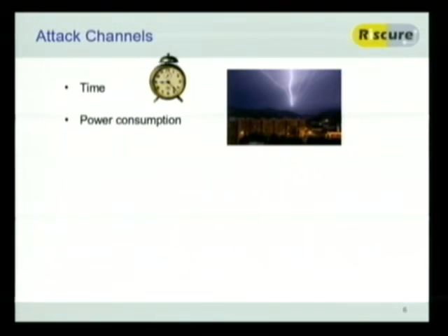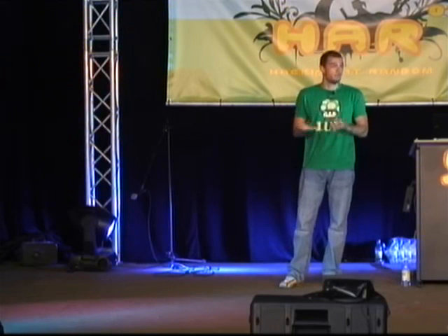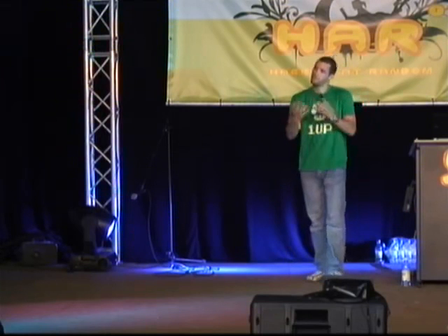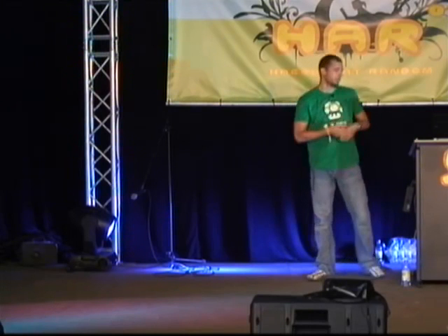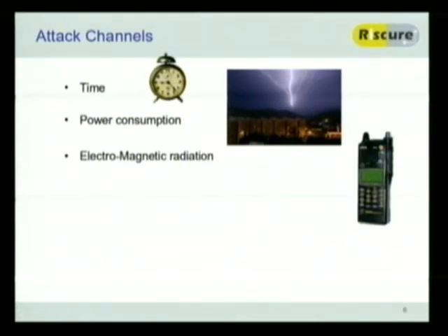Power consumption is one of the major side channels that we're going to be looking at. You can imagine that each device uses power, but when you really start measuring this precisely, you can see that this power actually relates to what the device is doing. So once you understand this relationship, you can say something about what it's been doing just from the power usage. Same kind of idea with electromagnetic radiation. Every device that uses power is going to send out signals as well, and we can analyze those too. I'll have a demo on that in a sec.